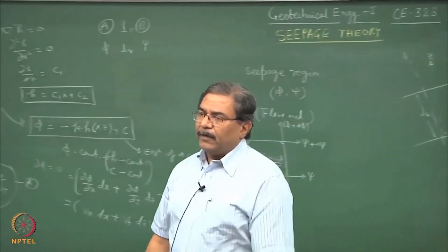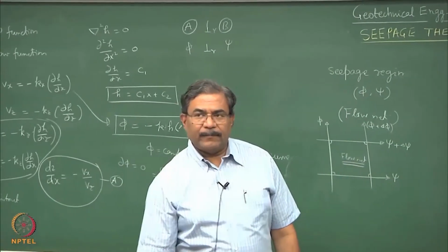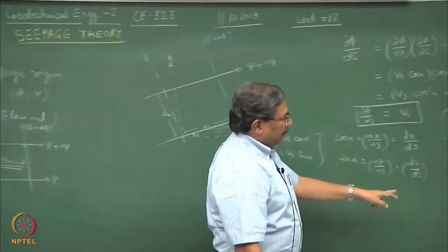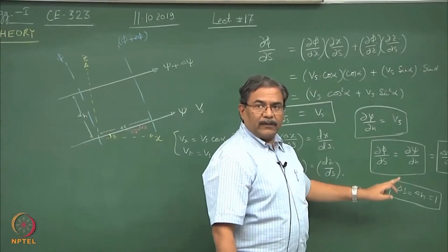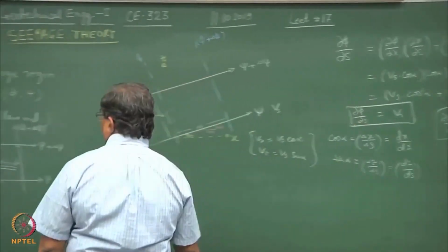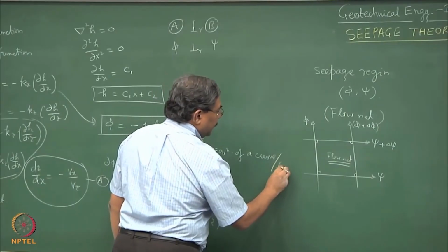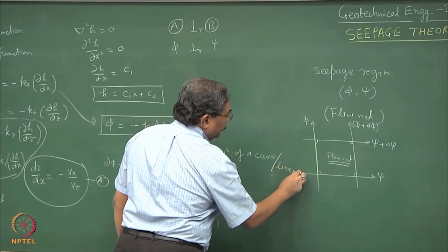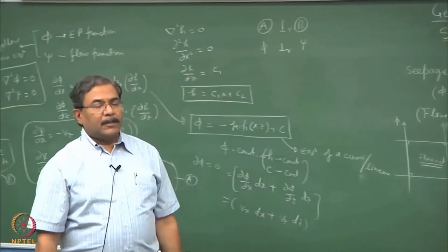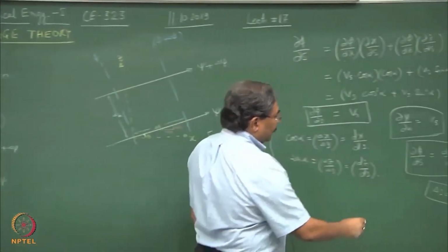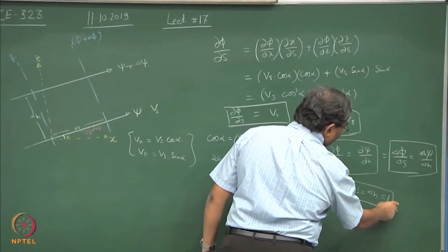So, this is the typical property of a square. That means the flow net units are going to be geometrically square, either they will be curves or they will be linear. So, there is no harm if I assume delta s equal to delta n equal to 1.